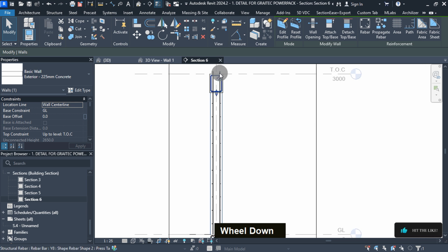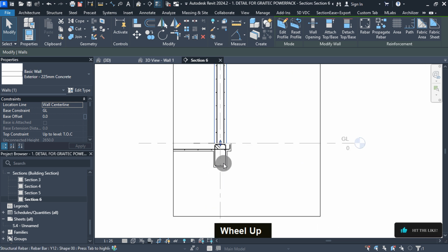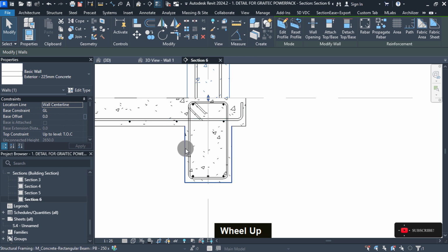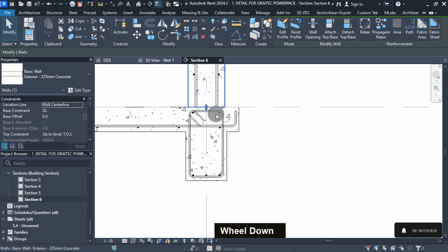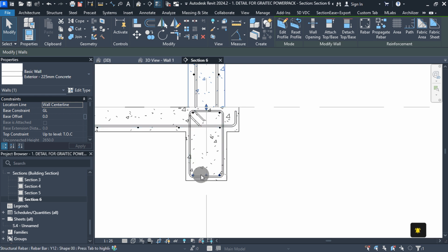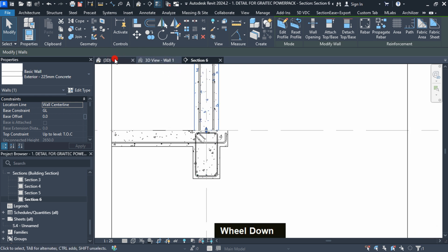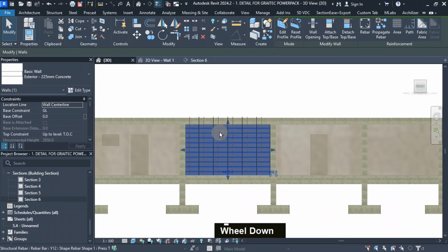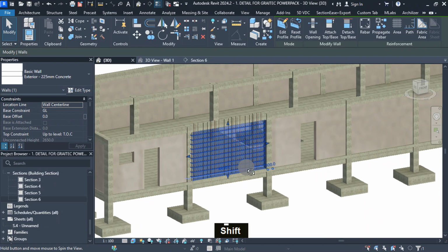With my design, I will explain how to get the correct values manually for the rebar offsets. I will extend the vertical bars up to the bottom beam rebars, then define a hook length and angle at the bottom and top of the wall rebar. Using this plugin, you can easily edit the rebar while in 3D view or any view within the model.